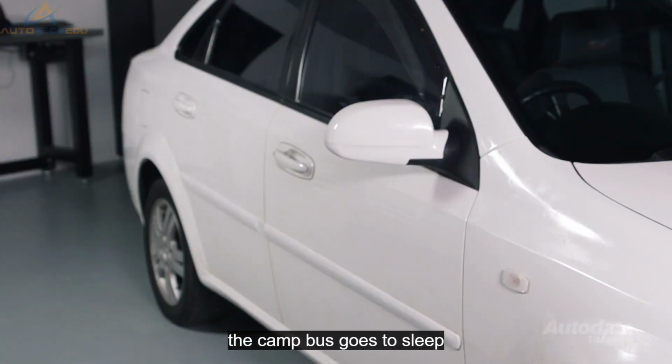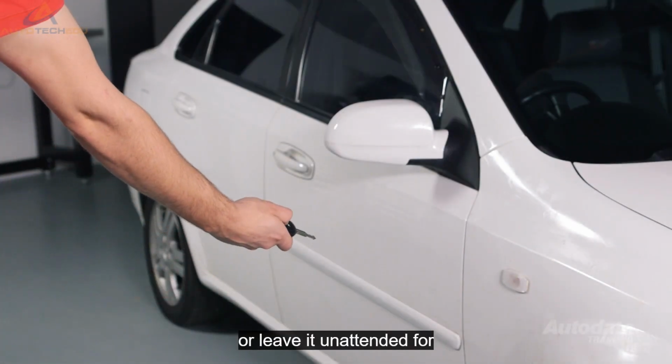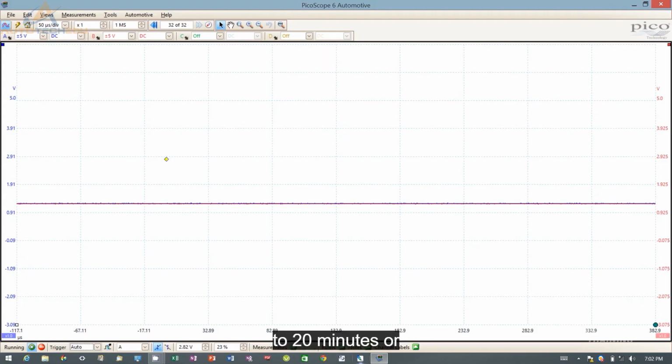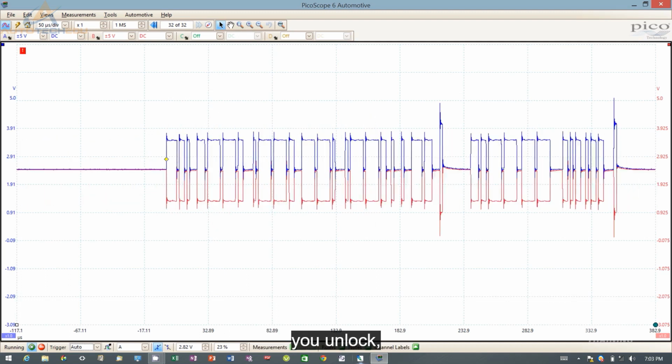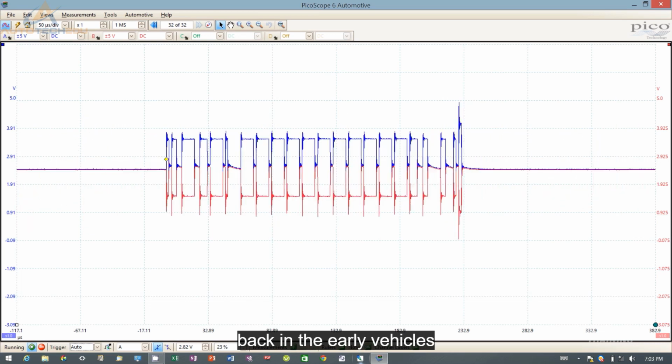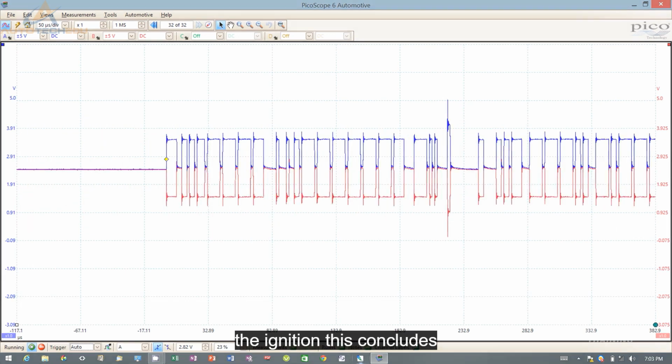The CAN bus goes to sleep when you lock your vehicle or leave it unattended for a long period of time. This can be up to 20 minutes or more, depending on the vehicle. In later vehicles, the bus will wake up when you unlock, open a door, or even insert a key, where back in the earlier vehicles, you had to turn on the ignition.